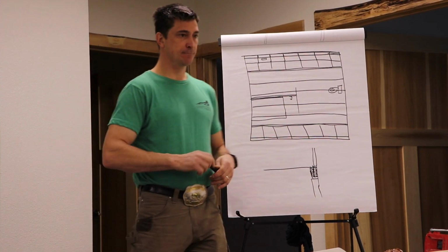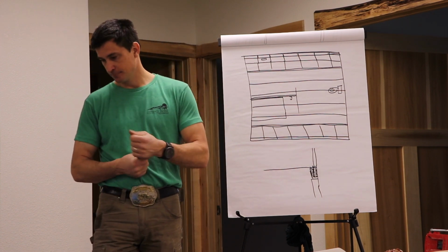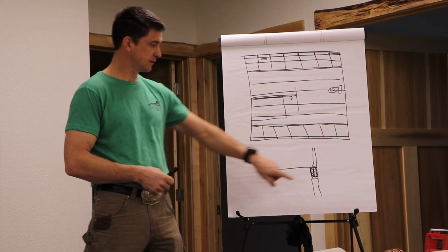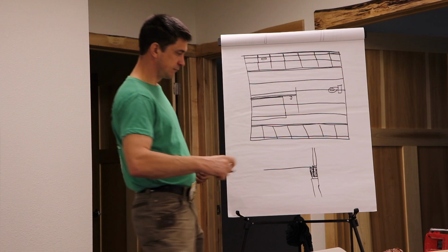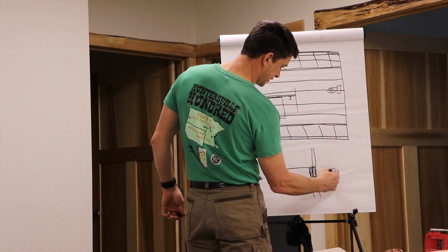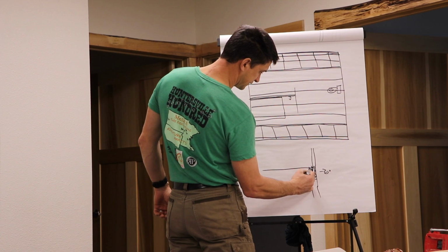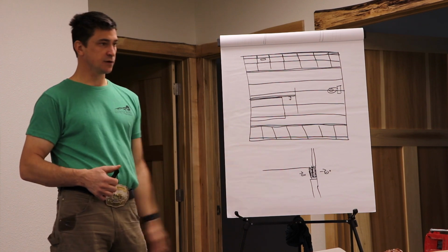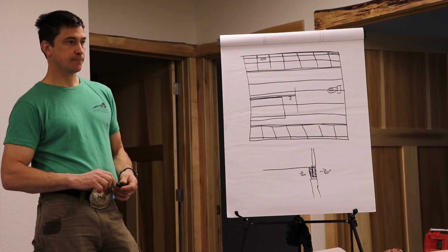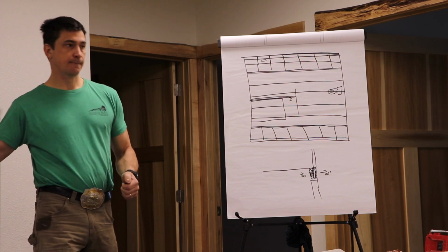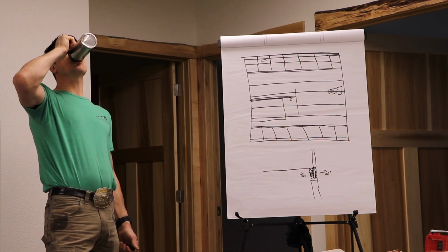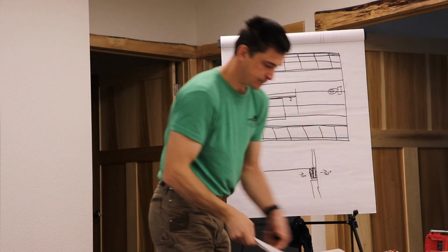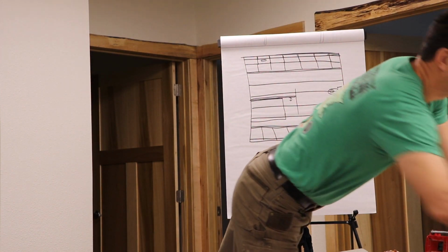Okay? Any questions on that at all? Why would you need to insulate down there? I don't really get it. Like this here. Right. Well, is that for the basement? This is minus 20 degrees outside, and this is 70 degrees inside. Okay, so it's a basement. Well, basement, or if it's a crawl space, it's still going to be warm. You're getting thermal bridging through that piece of wood right there to that open cavity. So you're going to get condensation build up on the floor sheeting. And then your floor sheeting rots out, your wood rots out. And then you've got all sorts of issues.